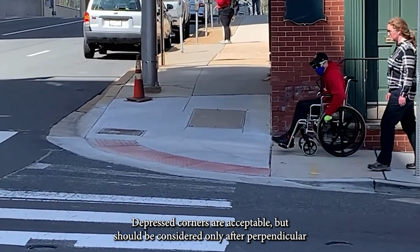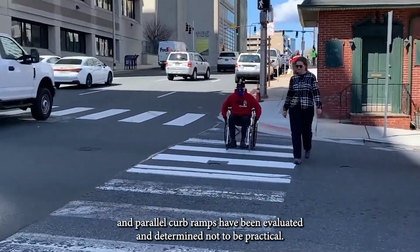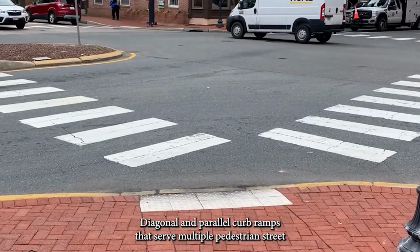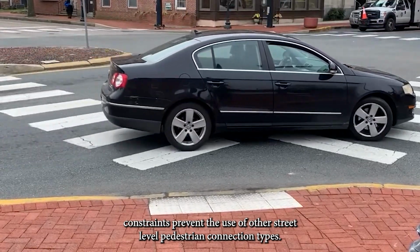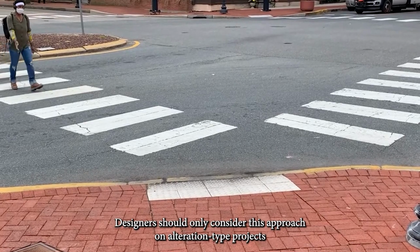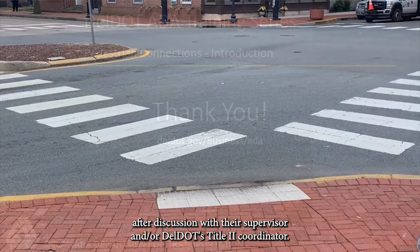Depressed corners are acceptable, but should be considered only after perpendicular and parallel curb ramps have been evaluated and determined not to be practical. Diagonal and parallel curb ramps that serve multiple pedestrian street crossings shall not be used unless existing site constraints prevent the use of other street-level pedestrian connection types. Designers should only consider this approach on alteration-type projects after discussion with their supervisor and/or DelDOT's Title II coordinator.